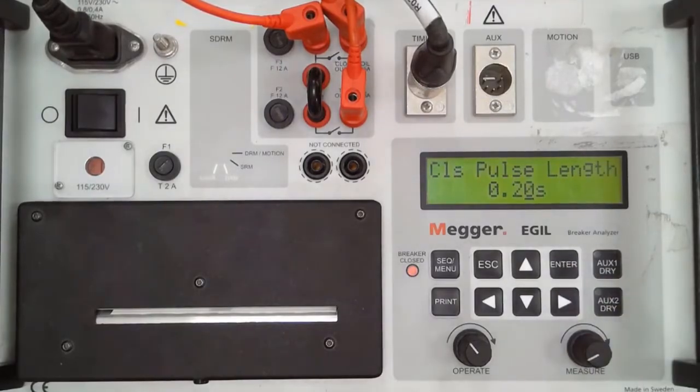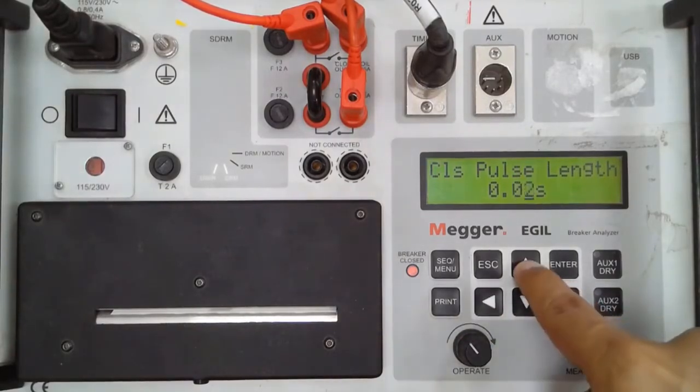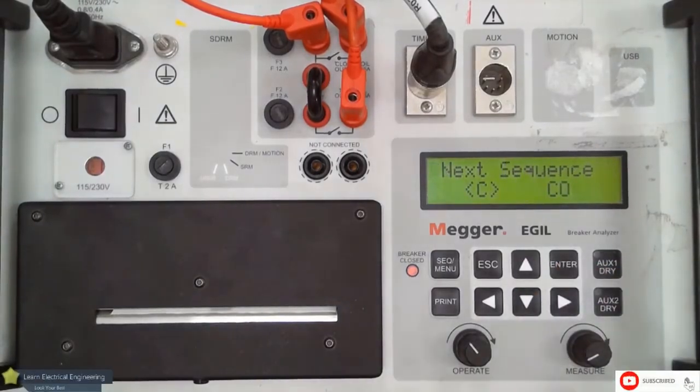okay, we explained in the video that will appear to you now the method of setting the close sequence and the open, close, open sequence. When we talked about the close sequence, we said we could give the close pulse about 20 or 30 milliseconds, which would be sufficient for the close coil to pick up and release its spring, especially for the close operation under the circuit breaker. It is not necessary for the close pulse to equal the closing time of the circuit breaker. That's why I will start by saying here 0, and then, for example, say 20 or 30 milliseconds and confirm it. All right, here I have the operate and the measure.